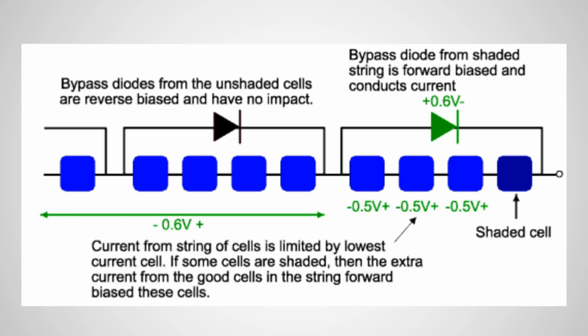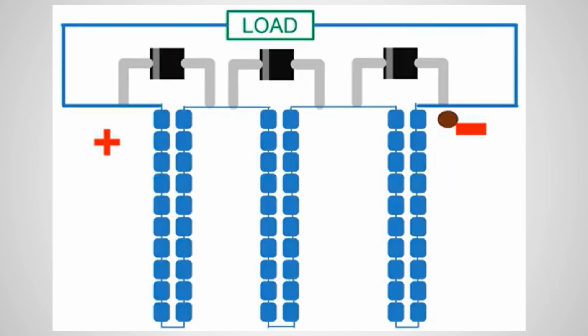Look here, we can connect this diode across a number of cells. It depends on the manufacturer's design. Here we have 4 cells and we connect the diode across them. In this diagram, we can clearly understand how this connection is working.